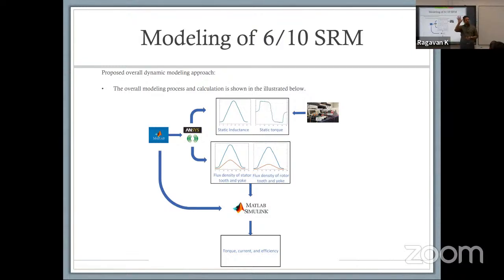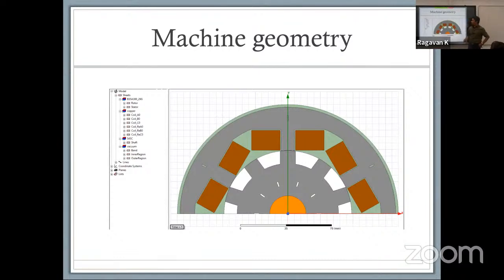Each one of the phases, you add them together. If you know the flux density and your static torque profile, you can combine them to recreate the behavior of the motor. I put this in specifically for anybody trying to design this in ANSYS. Towards the end, we won't have time to go over the modeling detail because the license for ANSYS is not available. But I asked one of my students to put together the steps so you have a reference available if you want to go back to how we did this. By the way, the folks at ANSYS are always happy to work with you.